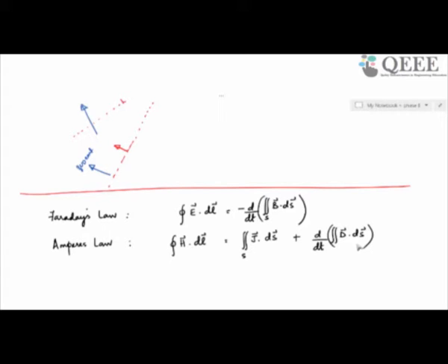to a magnetic field. Now after that we derived Gauss law from Ampere's law and Faraday's law. We applied it on a closed surface, and we derived that the closed surface integral of D dot ds, which is the net flux emanating from a closed surface, is equivalent to the charge enclosed by the surface, which is the volume integral of rho dV.